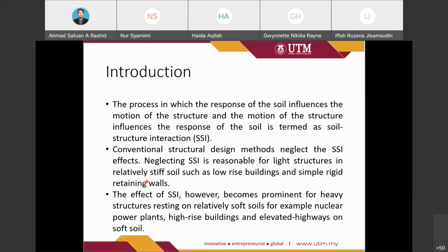For example, for a long span bridge, normally they use a rubber damper. When I went to the second Penang bridge, I could see a rubber damper between the bridge structure and the pier of the bridge. It is made from rubber, and it can minimize the effect of the acceleration of the soil.